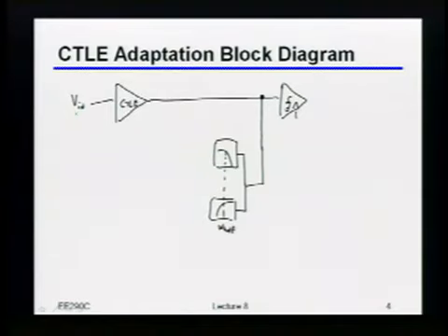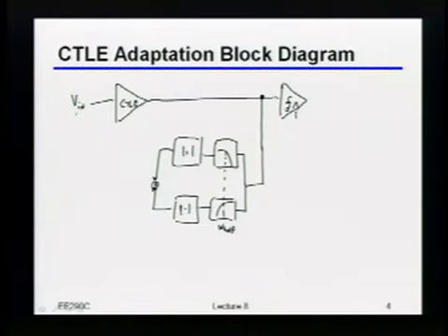Yeah, basically I just do a peak detection. So I do some sort of either squaring or rectification or whatever you want to call it. I'll just draw it as an absolute value here, although you should really think of that as a rectifier or a peak detect. Once I've got that, I know the energy in the lower band and the energy in the higher band. So now all I really have to do is compare them, so really just subtract them.